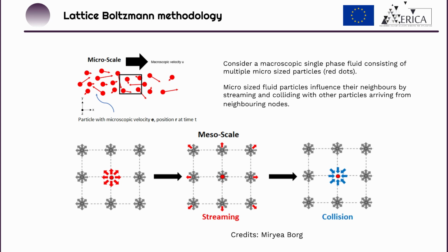The Lattice Boltzmann, as its name suggests, is based on a lattice network of equidistant nodes, noted in gray. A red node signifies a packet of fluid at that particular node, and this has the possibility to interact with its neighboring nodes by a discrete probability distribution function. This means that there are 8 possibilities for it to interact with its neighbors, which equate to the 8 red arrows, and 1 possibility for a portion of fluid to remain at the red lattice node.